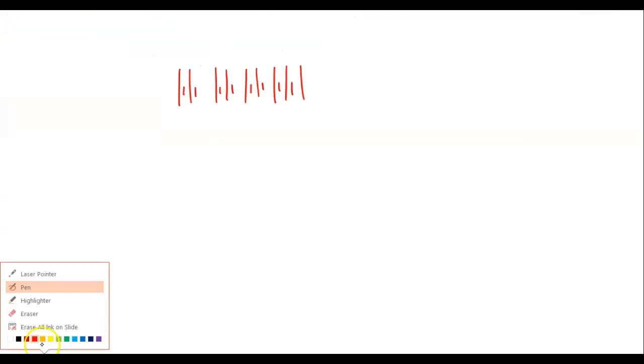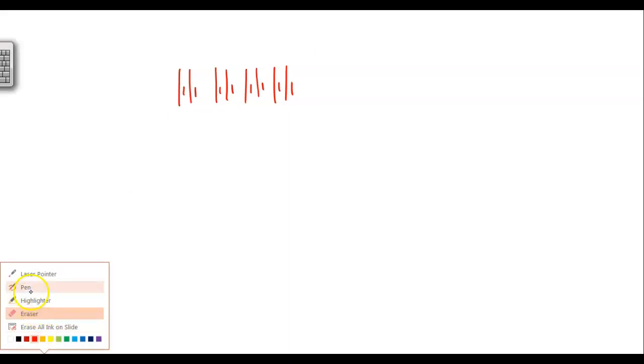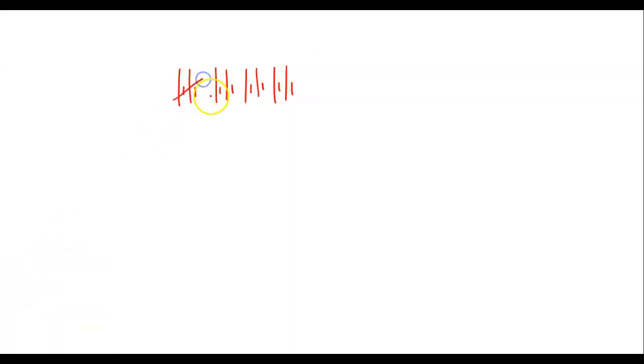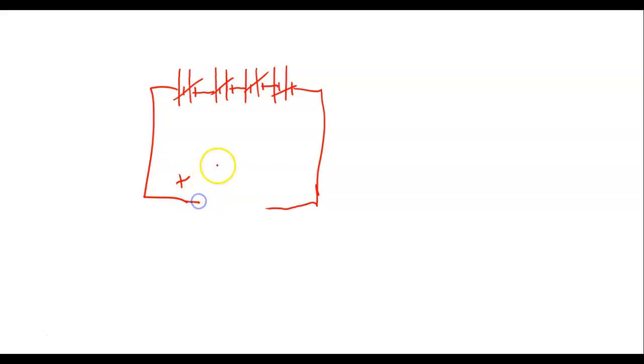We're doing 30, 60, and 120. So I've got 4 variable supplies. And this will be my positive. Then I've got them hooked in series aiding. And then I come over here, this would be my negative. So we've got the diode in there like this. And then we got a 1 mega ohm resistor right here.